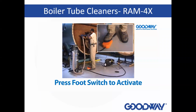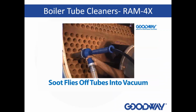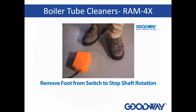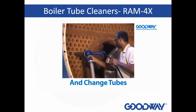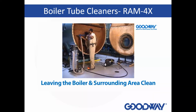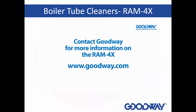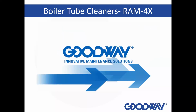So right here, he's stepping on the foot pedal, and what that's doing is activating the core of that shaft to start spinning at 862.5 RPM, which we consider is kind of like that sweet spot, that right speed for not being too aggressive, but being enough so that you can clean the inside of the tubes. You push the cable down the tube, and once the brush is spinning, it kind of helps itself along. It's not very labor intensive. And once you get to the end of the tube, you pull it back out and move on to the next one. And again, the rotary equipment is what we'd usually use for somebody that's cleaning a heavier deposit. This is going to be your most thorough method of doing a mechanical cleaning of the inside of a tube.